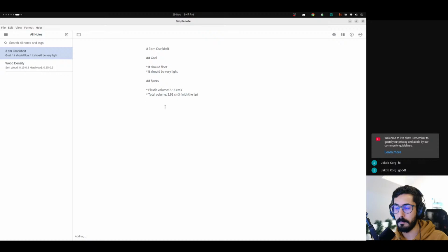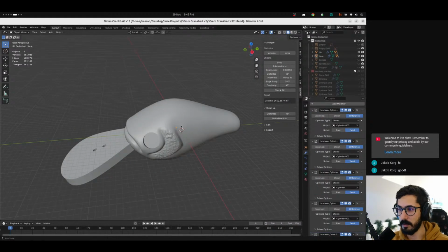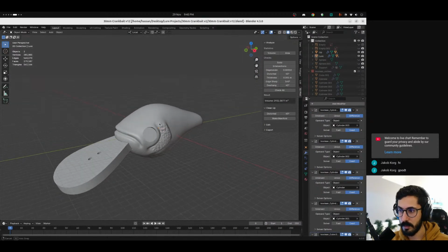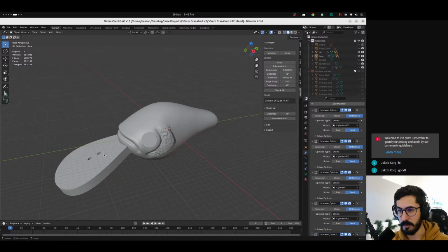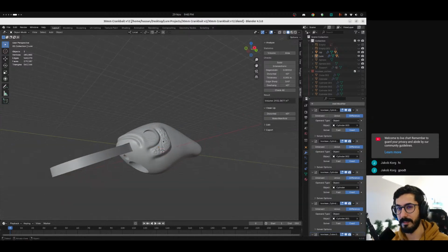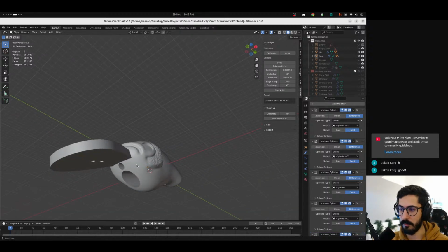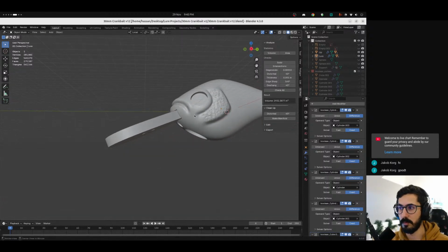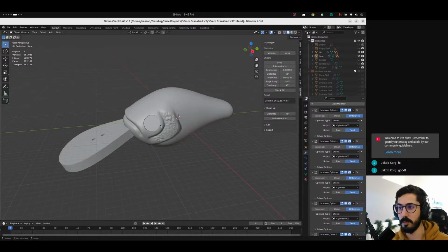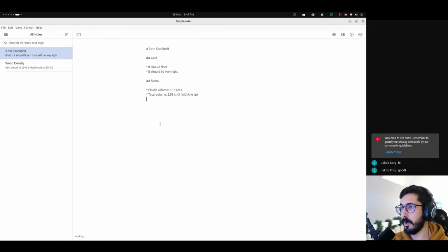And also, it will determine how we can print the lure, and I'll get to that in a bit, because for this specific lure, we're gonna reach a point where it's basically not possible to achieve the density that I want in this configuration. We might need to do a through wire, which is basically what you would do if you were using balsa, right? If you were using balsa wood, you would cut 2 pieces, put a through wire between them, and then sandwich them together. And I'll tell you why in a bit.